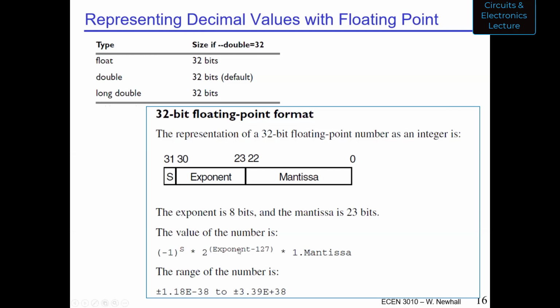Well, the answer is that processors, microprocessors, microcontrollers, can perform operations generally faster on integers than on floating point numbers. And so sometimes if you want speed, you use integers. If you only need 8 bits of integers, there's no reason to waste 32 bits, let's say, for a big array of values of floating point. Okay, so that's how fractional values are represented.